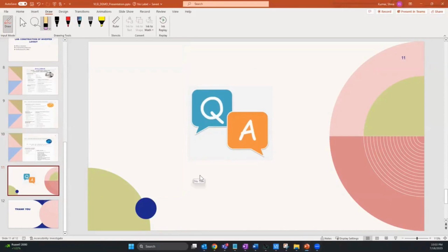The tool we use is Virtuoso, which is wrapped into Cadence. And for verification purposes, we use Assura, and we have Diva LVS, and we can also integrate Calibre. All three we can integrate. There is no limitation. But the plan I have is 45 and 90 nanometer. Those are the PDKs available in the market. So you will work on 45 and 90 nanometer with the Assura tool and Diva also, and we can integrate Calibre also. But Virtuoso is common. These verification tools we can integrate. That's not a big deal. We can do that.